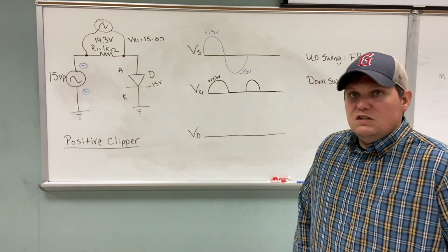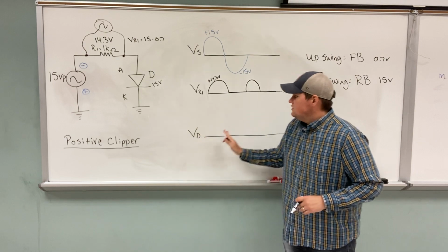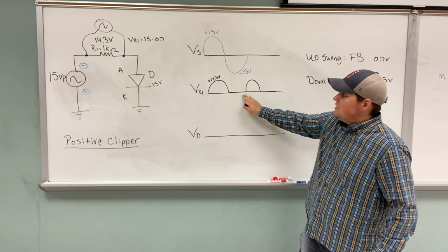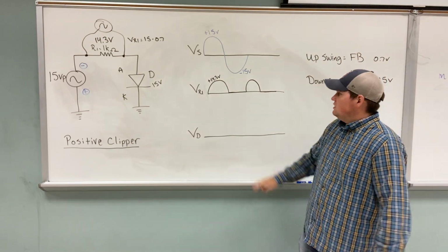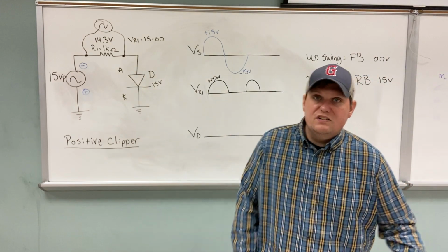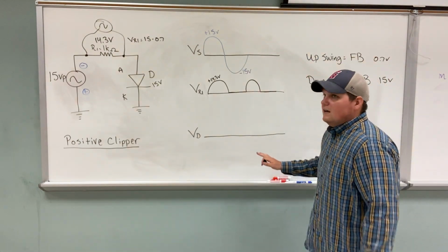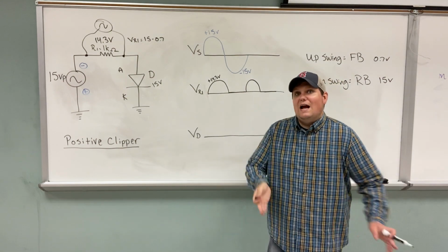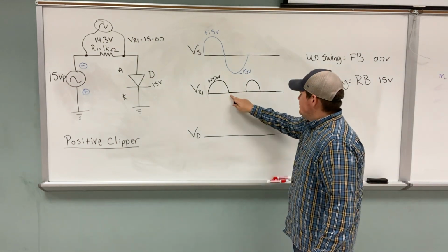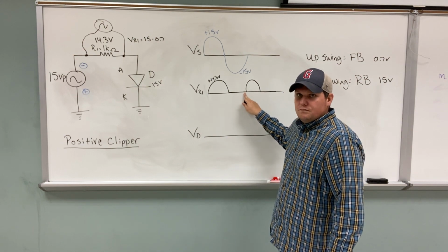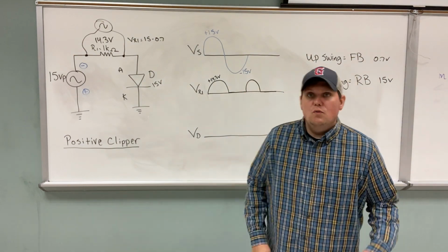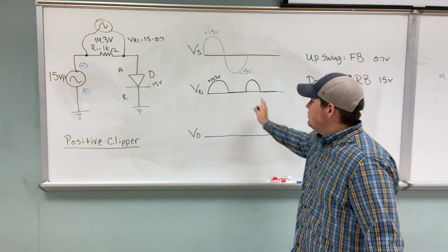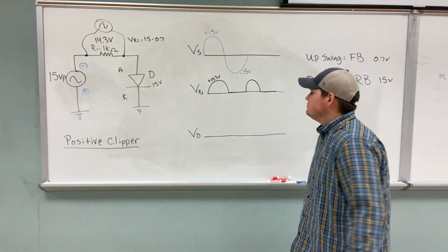Okay? So that means that this is where I'm seeing that DC. Because if you look, basically this is just a half-wave rectifier. I'm allowing current to flow in the positive direction, but when it tries to flow in the opposite direction, it's not allowed to flow. All right? So, essentially, current's only flowing one direction here. So that's why I say in the most basic form, this is DC.